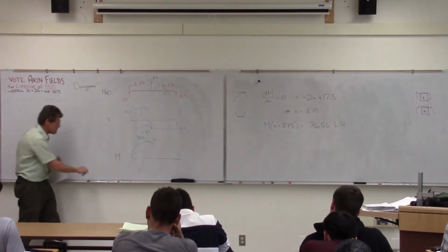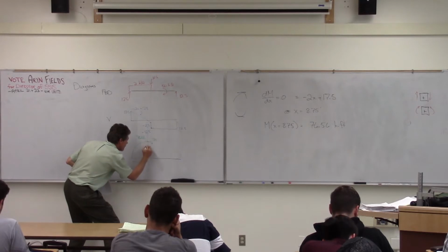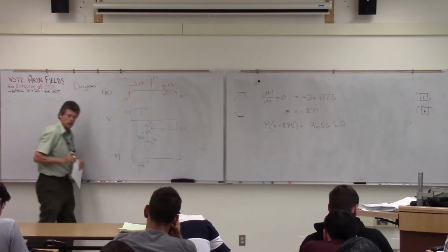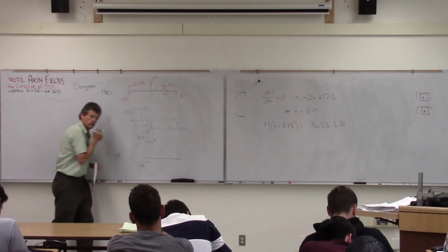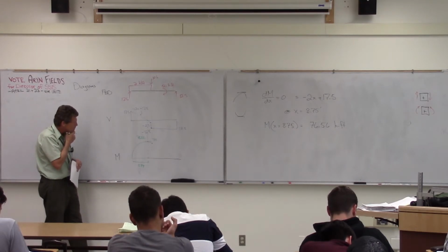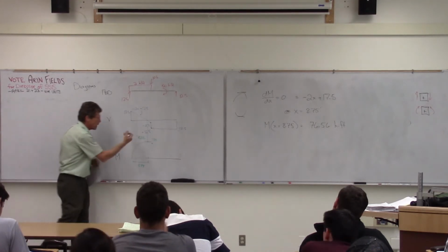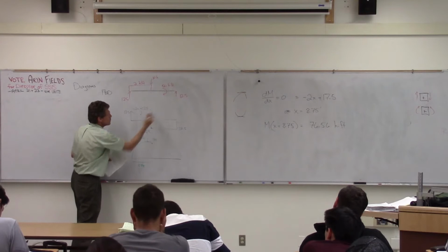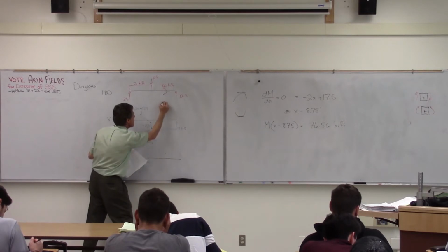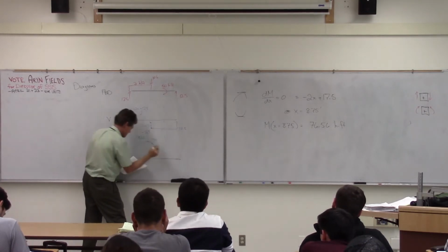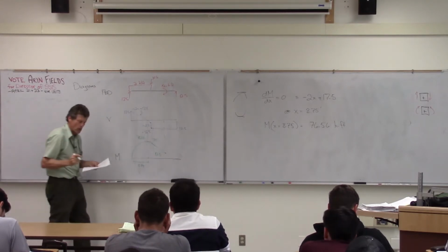But the key thing is that my max now is at the 8.75. And as a designer, I need to know that, because if I'm going to be putting steel in reinforced concrete or beefing up my compression flange in my steel section, I need to think about, okay, what's the highest? Do I need it everywhere? And that sort of thing. Okay, then as we look at what's going on, it drops down to 12.5.